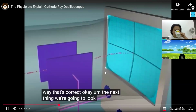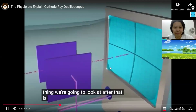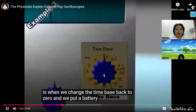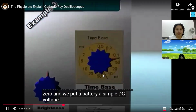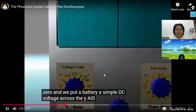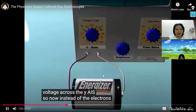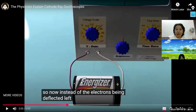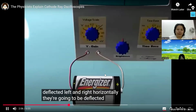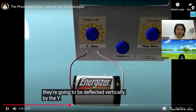The next thing we're going to look at is when we change the time base back to 0 and we put a battery, a simple DC voltage, across the y-axis. So now, instead of the electrons being deflected left and right horizontally, they're going to be deflected vertically by the Y plates.